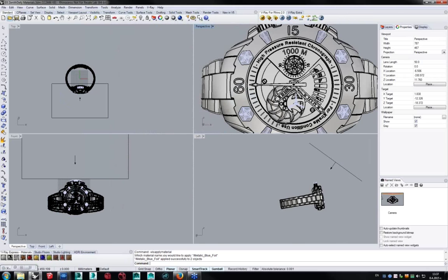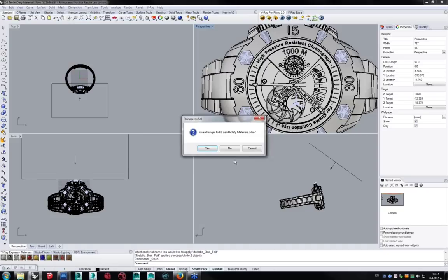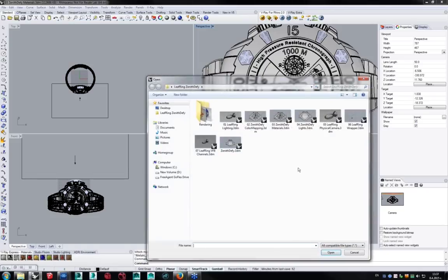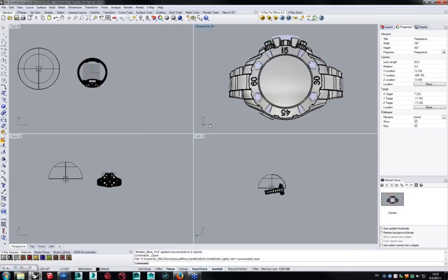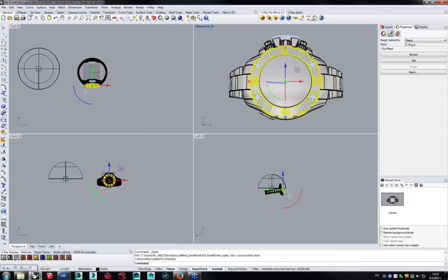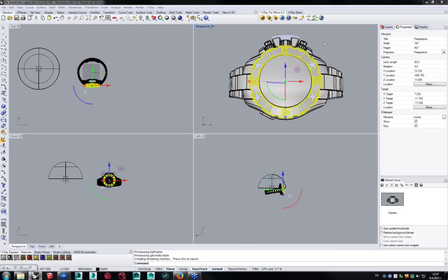So now the next thing that I want to show you guys is how to build the actual light setup that you want to have for the final rendering. Now let's say you have done or partially done your materials, you have applied them, and you want to start adding lights that will highlight and emphasize your model. So there we go. Let's again use the V-Ray RT.